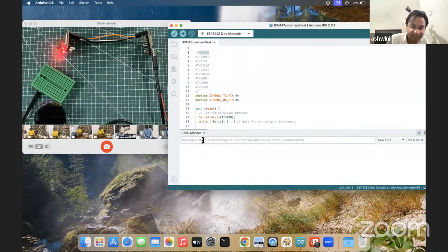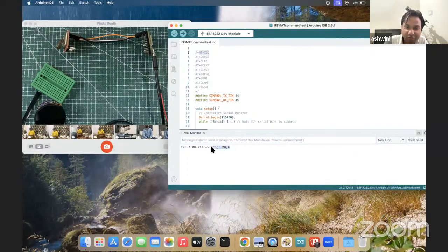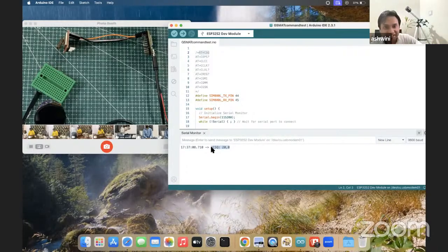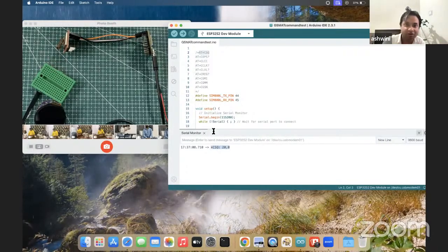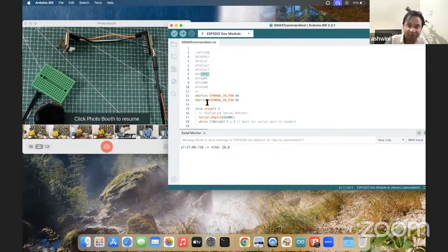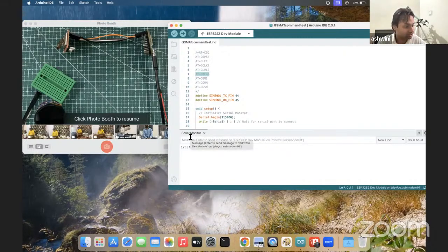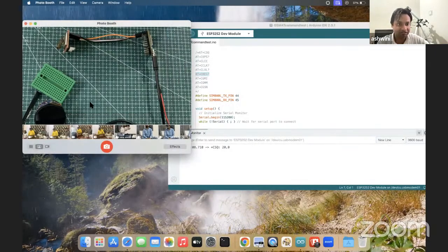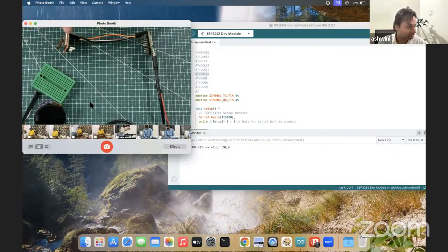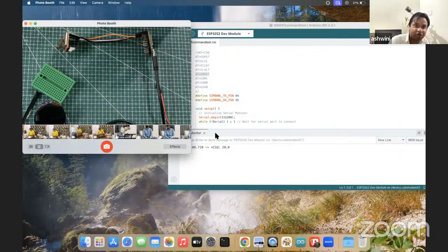When I send this AT command, it will tell you the volume level of the chip. If you want to increase the speaker volume, low or high, you can do that. Using this command, we will check the network status, whether it is connected to the network or not. When I send this command to the GSM module, it will return the output to the Indus board and then to the serial monitor.